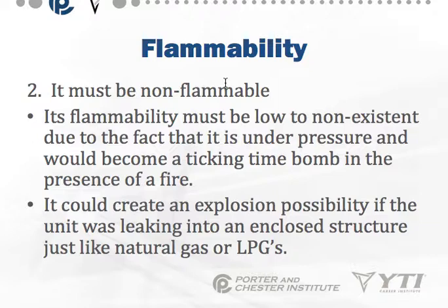We need to be careful on this because there are some newer systems coming out that actually use propane to cool as a refrigerant. So just be aware, and just as a little side note on here, if you ever see a system that has propane as a refrigerant, you cannot use the identical tools you use with other refrigerants, and you got to be very, very careful and get some special training.